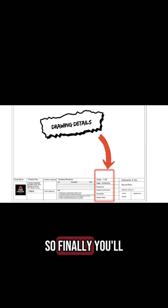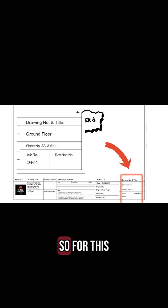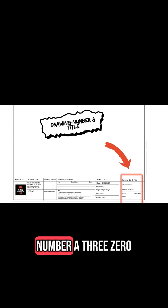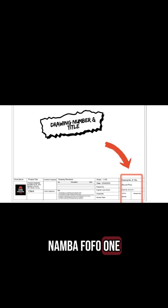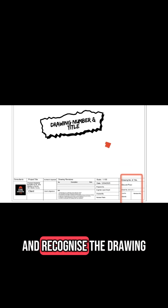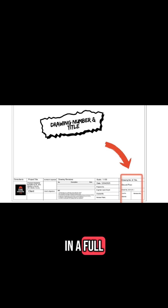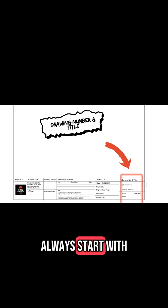So finally, you'll see the drawing title and number section. For this one, it is titled ground floor with the drawing number A301.1, job number 4410 on sheet A3 and revision 0. This helps you to easily identify and recognize the drawing, especially when you're having multiple sheets in a full construction set. So before you jump into reading walls, doors, and measurements, always start with the title block.